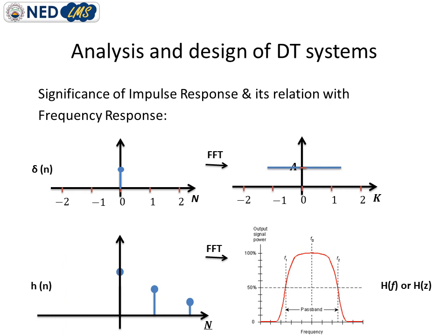So one is the time domain view and the other is the frequency domain view. So that is very much interesting. So this is the shortest as well as the fastest way to determine the system characteristics: take the FFT of the impulse response. And how do we get the impulse response? Just by applying an impulse at the input and observing the corresponding output, because that output is the impulse response.